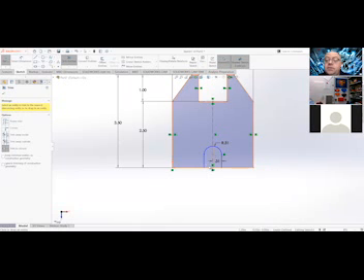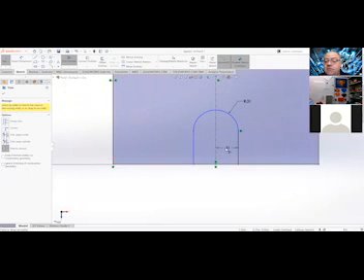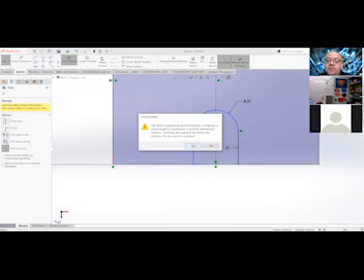And the reason we're in blue is we don't have a distance for where this is positioned. We have one here. I deleted the other one when I did my trim, so that's why it's not as clean. So while I'm in the trim mode, I might as well open it up. And again, like in AutoCAD, when you float over it, what's going to be cut is highlighted in orange. So I'm going to take that.